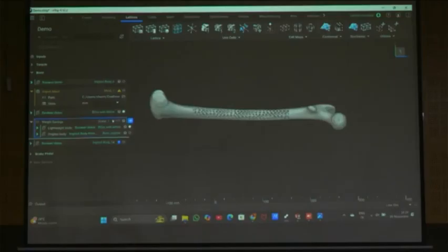Topology optimization will take the load simulation actually, and generative design also will take it. The basic idea of generative design and topology optimization is that we need to get the best result. Your objective is to get a good result by maximizing the strength and reducing the weight, and the constraints are that it should not remove this material, the passive region and non-passive region, the design space and non-design space, and it should not exceed this much stress. According to that, it will generate the design or optimize the body, which we call topology optimization. The algorithms are different for both.